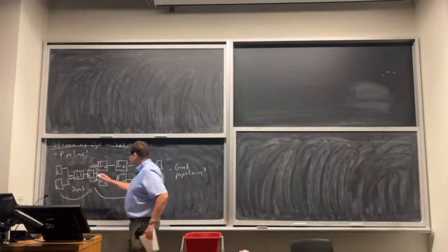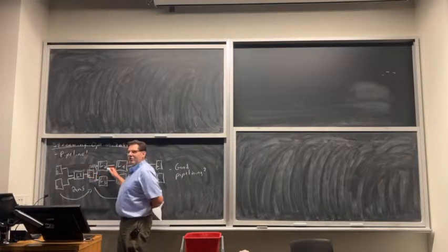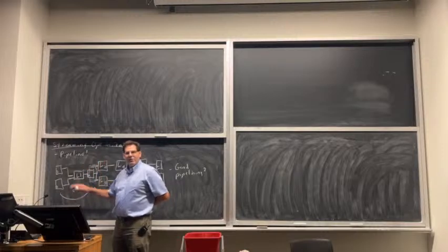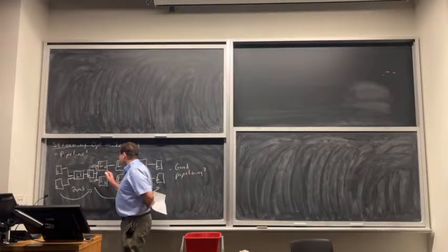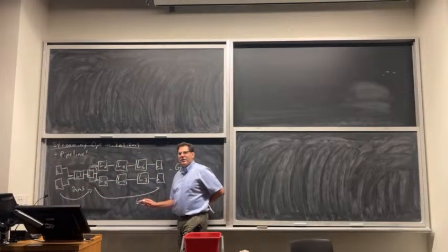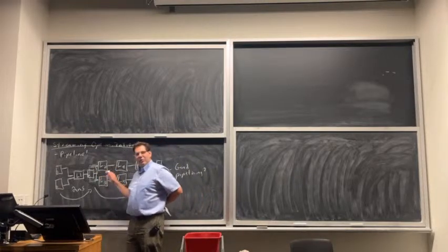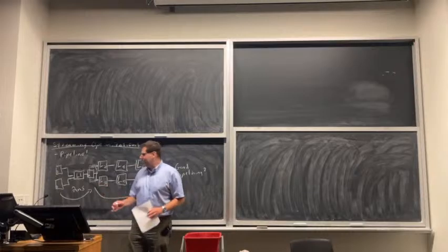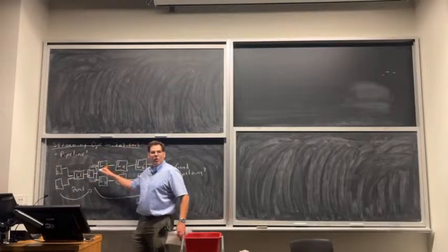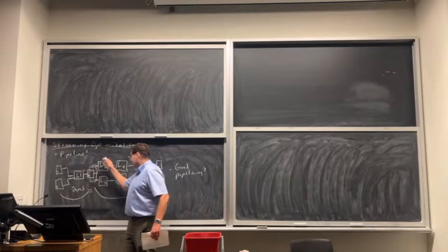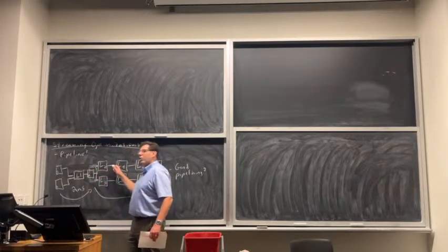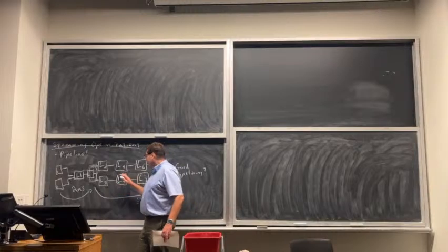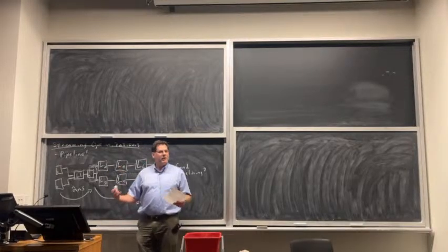So it's not quite as good as we might have hoped. So you can say, well, you didn't do a very good job pipelining. Put your pipeline registers there. But that's iterative, right? A human's now got to try it, see where they go, move them. It also can be a bit tricky in your HDL. In your HDL, you don't actually have lookup tables. You have lines of code that are doing things. Maybe I was doing some AND and then some OR or some kind of decode. It might not be obvious. Well, what line of code do I change to move this register over here? Because you're not editing lookup tables.